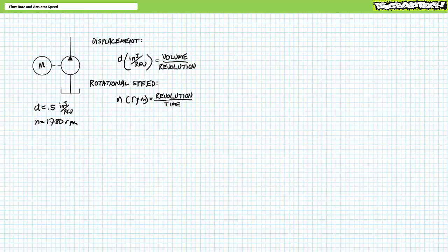Two aspects define fluid power: pressure and flow. We'll examine pressure, Pascal's law, and pumps in greater detail in later lectures. This lecture restricts itself to flow. A common pump property is that of displacement, which is a measure of volume per revolution, meaning every time a pump shaft is turned one full revolution, it introduces that much volume into a hydraulic system.